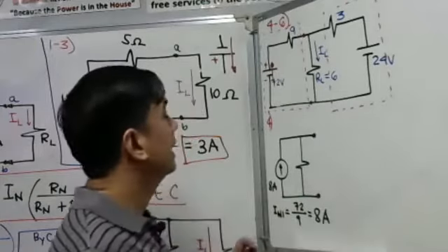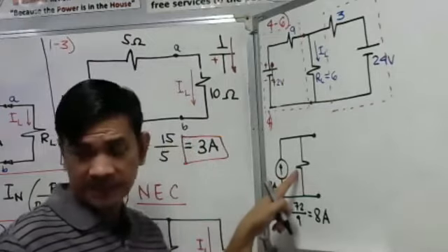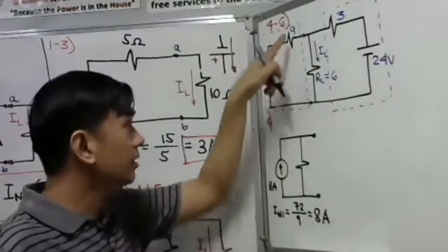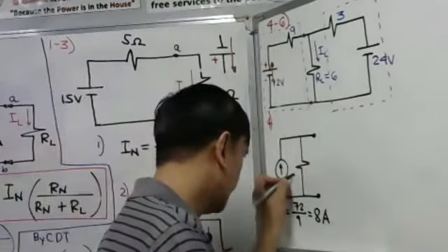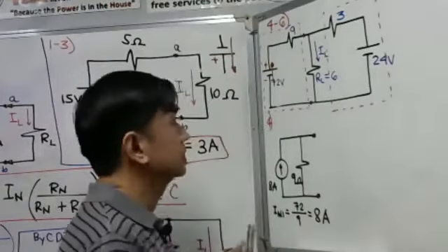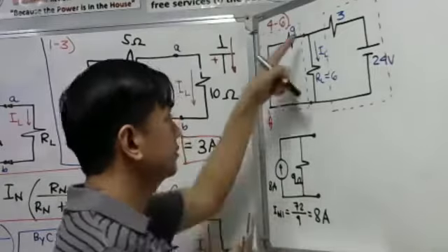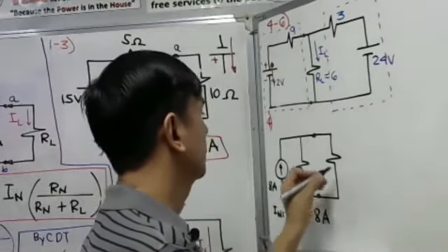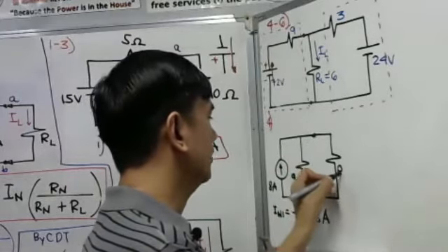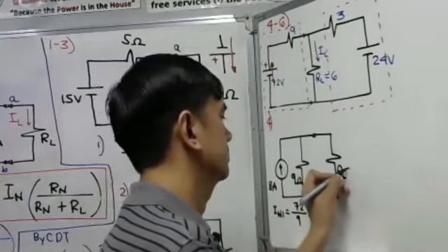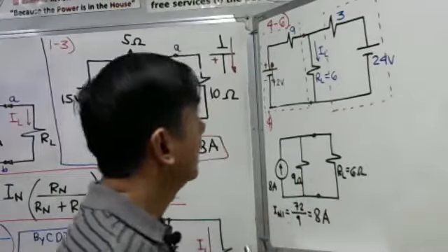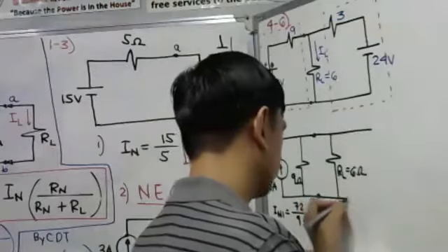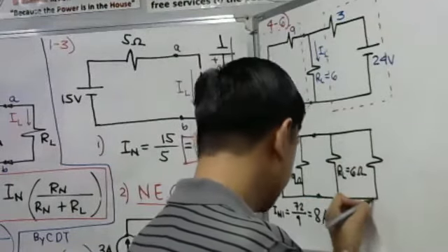And then, what is this resistance? This is our Norton's resistance for this particular Thevenin circuit. So, just copy that one, 9. Just copy that. That is 9 ohms. And then, the 2 points, we have here our load resistor, our 6 ohm resistor, this is our RL, equal to 6 ohms. And then what about on the right side? This will be the equivalent Norton circuit. The Norton's resistance on the right side.